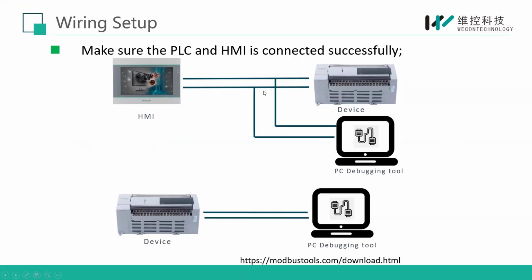Okay, so this way you can check the data. Suppose here you have one device, a PLC, and you want to check its data in the HMI, but it is not communicating. Still, you want to debug where the problem is. So you can use the online PC debugging tool.